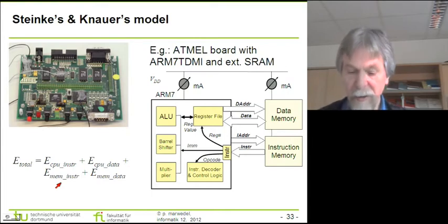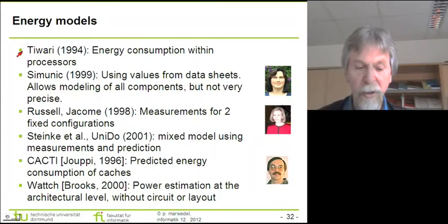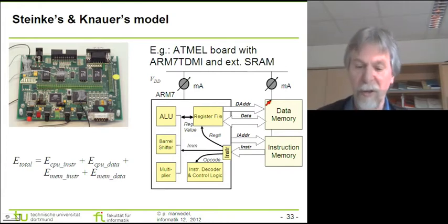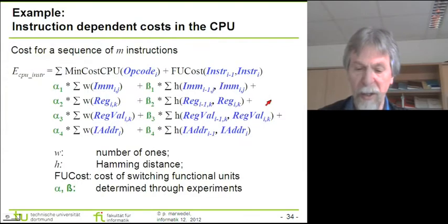So one key extension over the earlier work of Tiwari is that now we are analyzing the energy consumption both in the processor and in the memory. In order to do this, we cut the power lines to the processor and we cut the power lines to the memories, and then we were running very long sequences of assembly language programs and tried to figure out what is the impact of certain instructions on the currents, and multiplying by the voltages we were then able to obtain power and energy consumption.